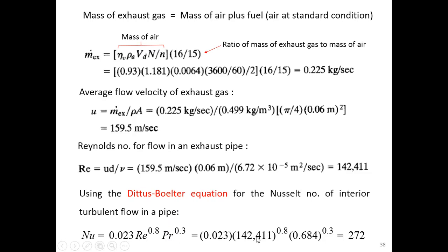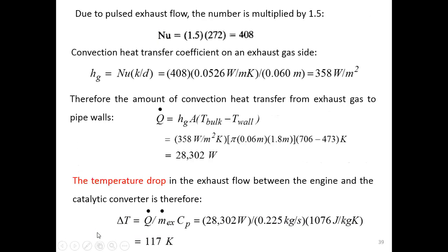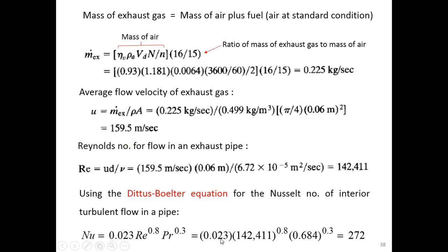The Reynolds number we already know, the Prandtl number we already know, so we know the Nusselt number here. And through the Nusselt number, we know that the Dittus-Boelter equation comes out from steady flow. Usually the Nusselt number equation is from experiments on steady flow.